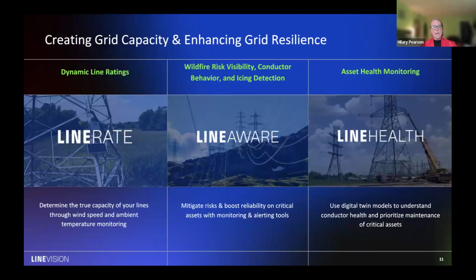So, what's exciting is that there are a growing number of tools available to help meet increased data center demand. And I think the role of dynamic line ratings in particular is critical, given its ability to bolster transmission capacity by as much as 40%. That's a significant jump that can help to energize more load on the grid now.